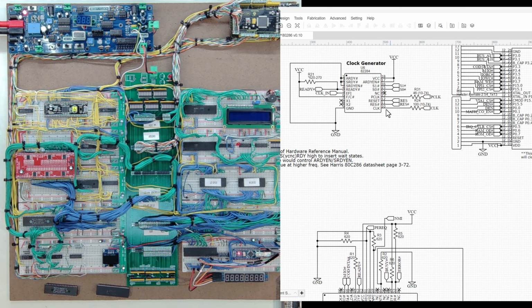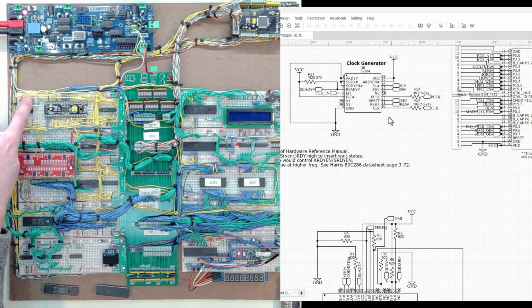And I think that's both on the clock and the peripheral clock coming out of this chip. I was running a 10 on the clock, and I decided, well, let's just try a different value. I tried a 46 because I'm using a 46 over on the peripheral clock, and that didn't help. So I thought I'd try the high end of this, which is 74. I didn't have a 74, so I put a 100 in. And that change made everything work.